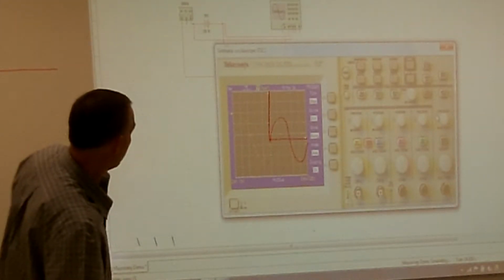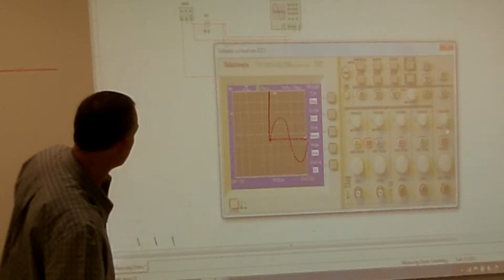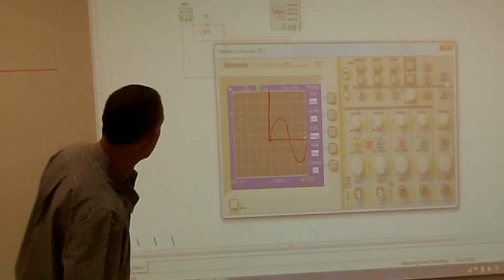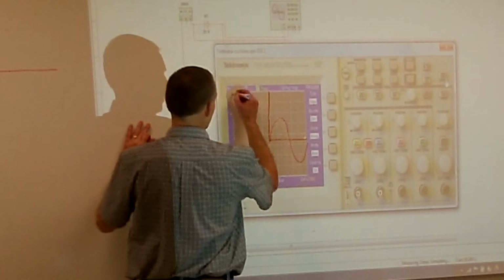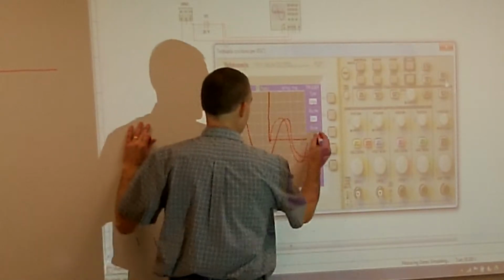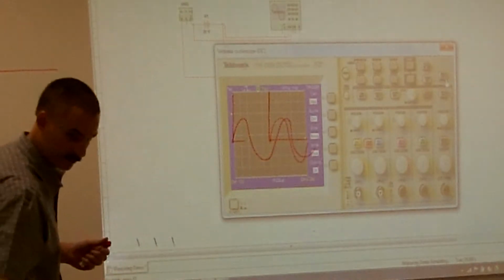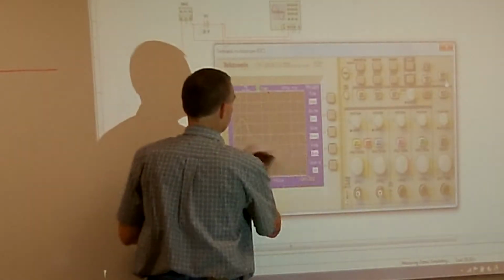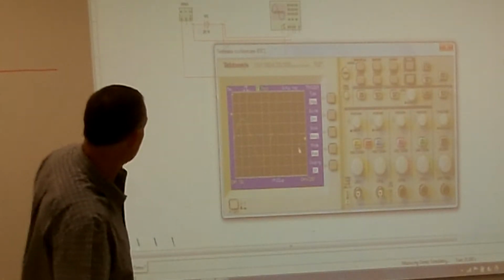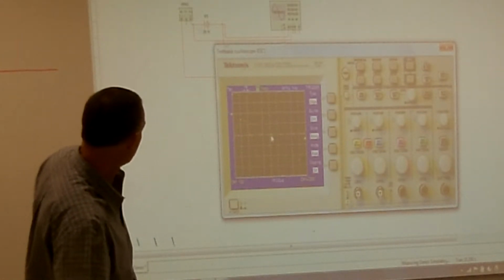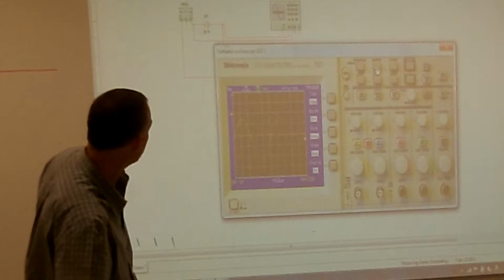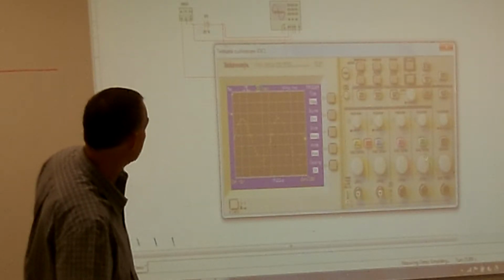If I want to, kind of like when we were doing it on the other one, I can move that position over to the very far left. Now what I did is I just moved this over to here. My trigger level stayed right here. Here are my crosshairs, and now I'm starting to draw right at the beginning of the waveform. So we can move around the position of where it's at. All right, so you wanted to have one complete cycle in there, so I have one complete cycle. I know I can't go any more than that because I'm a little bit over 5 divisions there. So I'm going to click on. Maybe I can go.